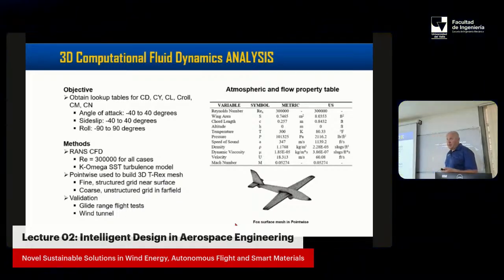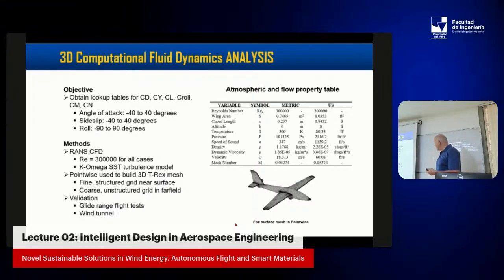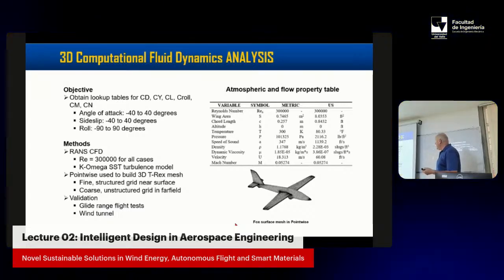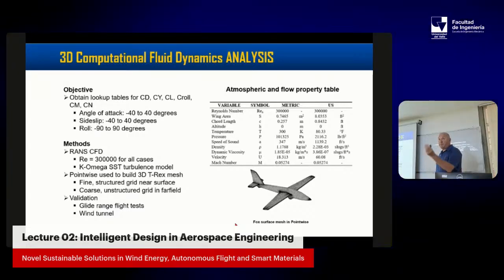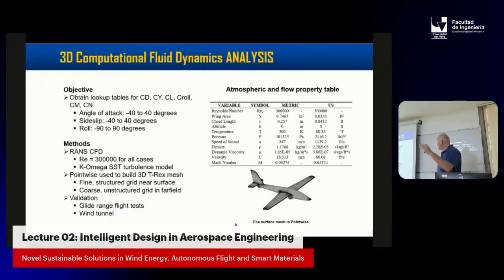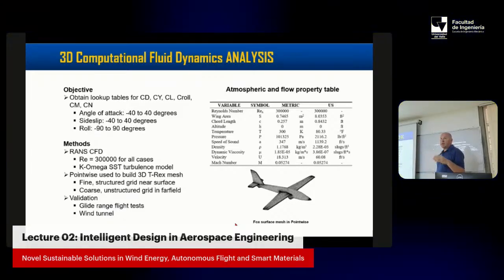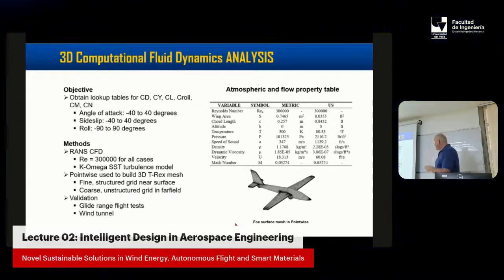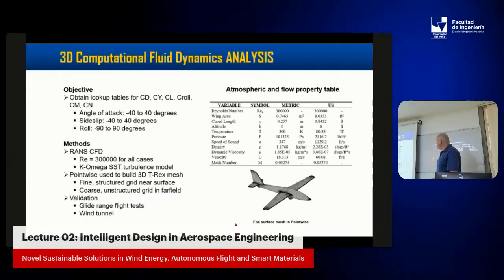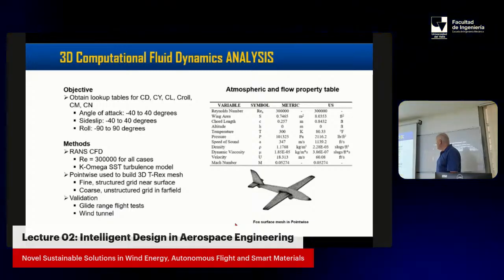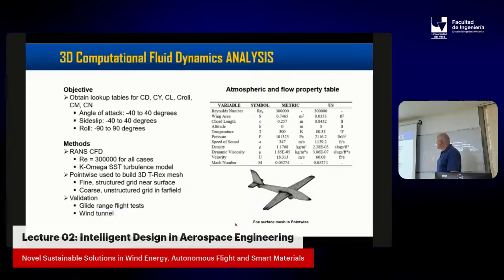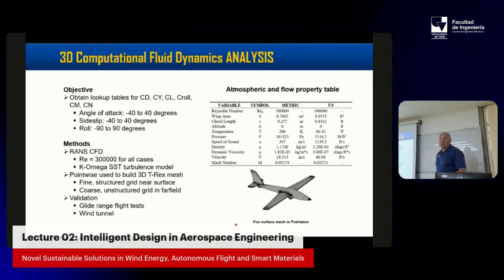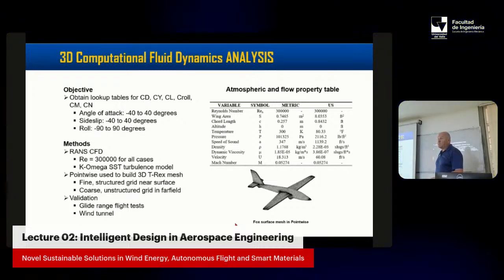If you want to develop an algorithm like this, you need to predict how the aircraft will behave at each step. When you go to this kind of maneuver, you go to very high angles of attack, doing the roll, doing the plunge, everything. So sideslip, all these elements here, usually range from minus 40 to 40. Of course, it's not just your panel method, because there's a lot of separation going on.